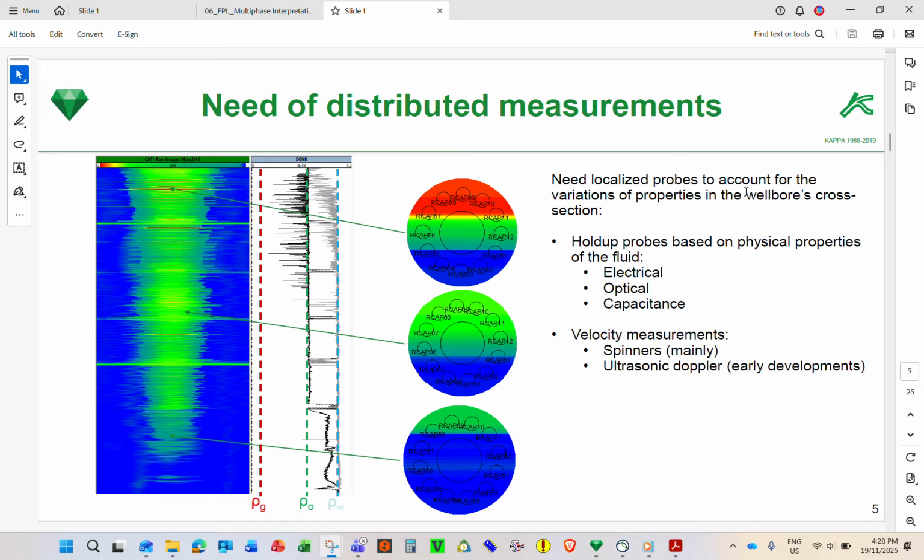But again, in this case, you might be reading just oil, but you might see it changing. So you can see the rotation. This is 12. See, the 12 is here, 12 is here, 12 is in the middle. So you might see that when the tool is going up, this is changing. It's rotating while going up or going down. That's why we need to know where the water level is on each different slice, and you can see it from the capacitor array. You might have gas at the top.